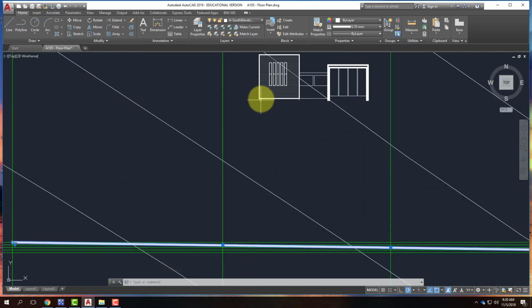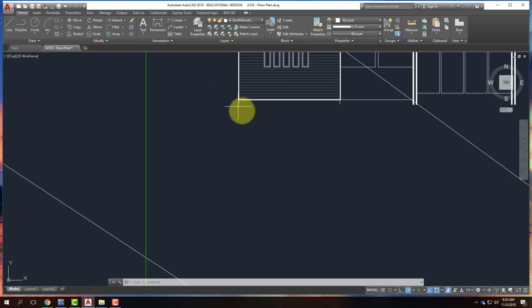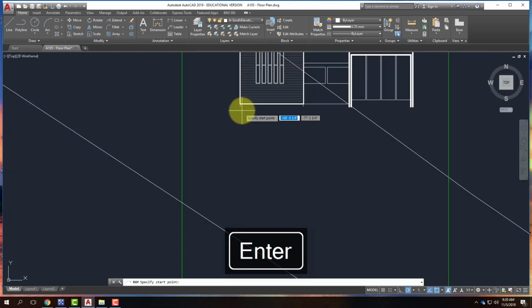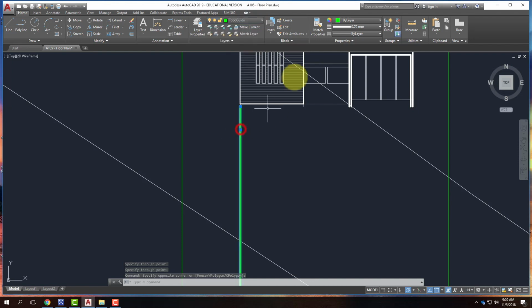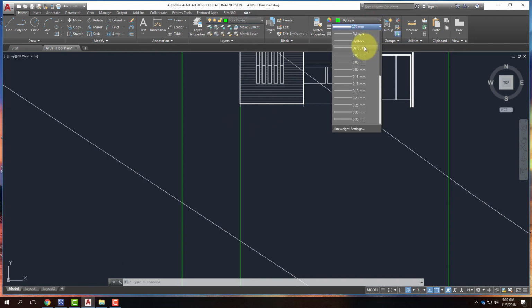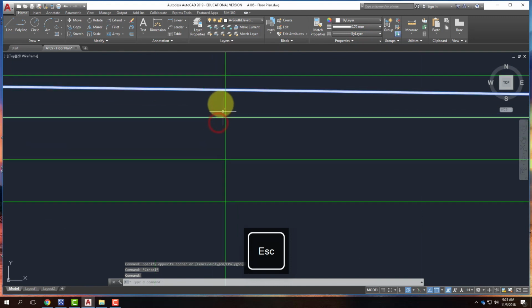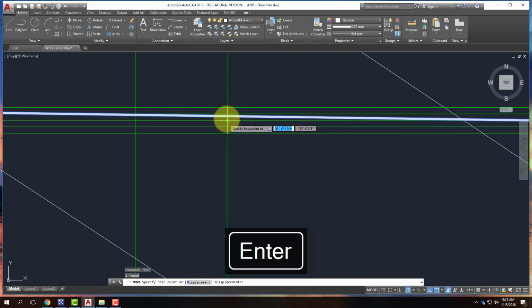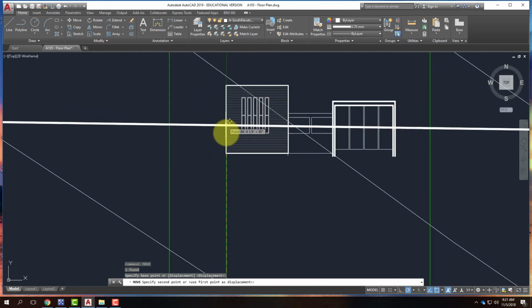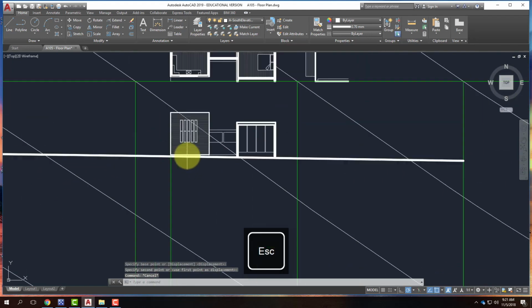I'm going to move this up to meet that first 8-inch point right there, so I can create a ray that goes from right there down. This should be on the topo guides layer, and needs to not have thickness. I will take this. The reason I created that guide is so that I can move it directly from the intersection of those 2 lines, and we'll come up to where I meet that point.